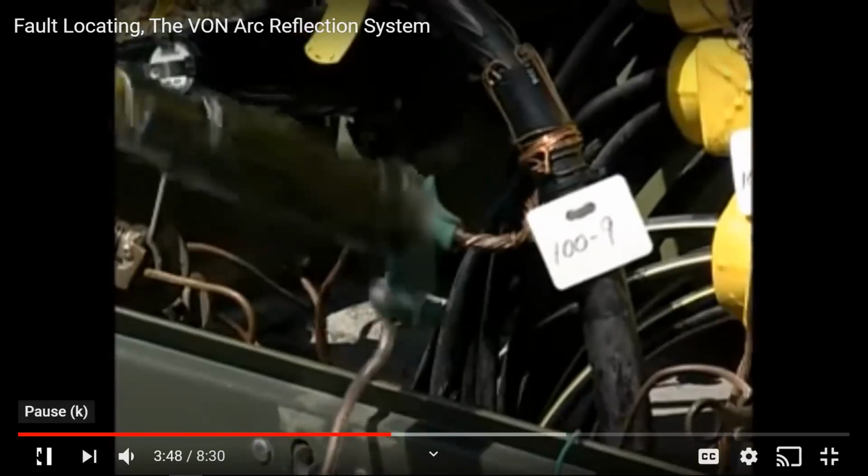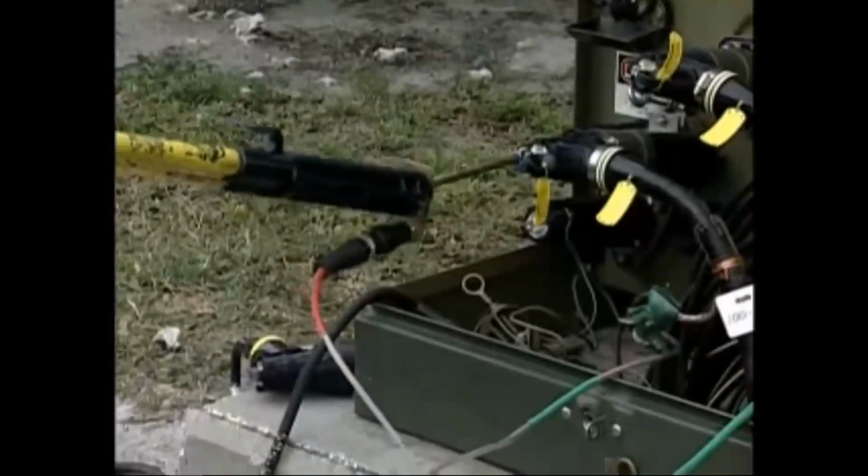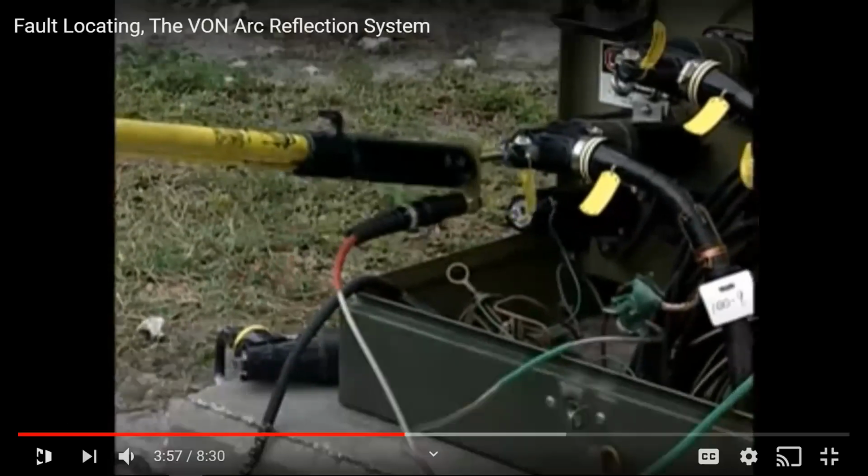One's the safety part of it, and the other one's the neutral return path. Next, remove the grounded elbow. And finally, insert the brass elbow probe attached to the high voltage lead into the bushing. Okay, this is the high voltage one where I'm going to inject a high voltage thump onto the conductor. So it's going in here through the feed-through, and it's going to be going out this conductor right here.